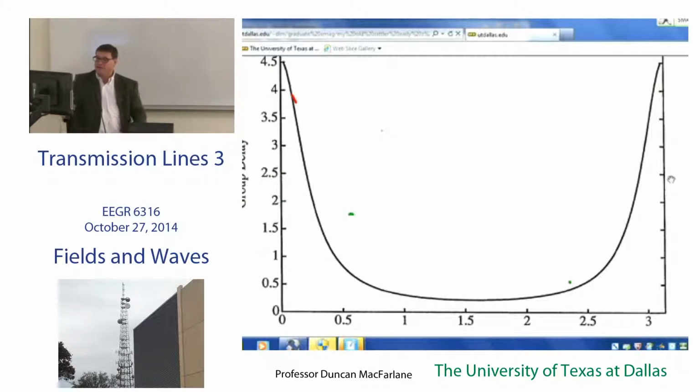And that answer, for a given frequency, is the group delay, which is the derivative of the phase response. So to me, the group delay measured in actual time is a little bit more meaningful than the phase response of a filter. But again, your mileage will vary. It depends on what you like to work with.